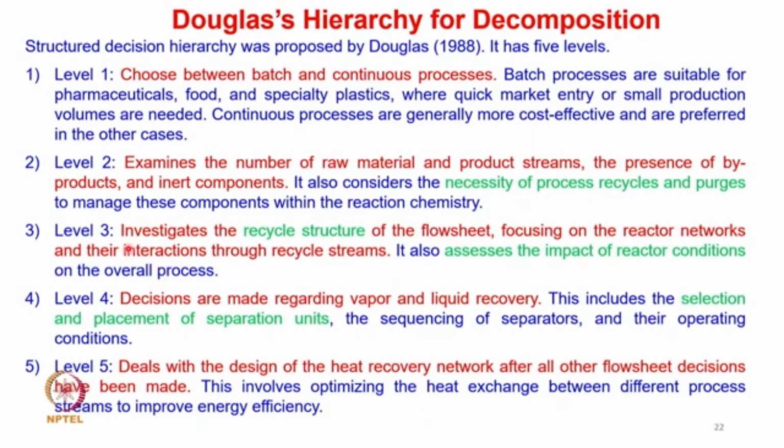Level 3 is to investigate the recycle structure of the flowsheet, focusing on the reactor network and its interactions through recycle streams. It also assesses the impact of reactor conditions on the overall process.